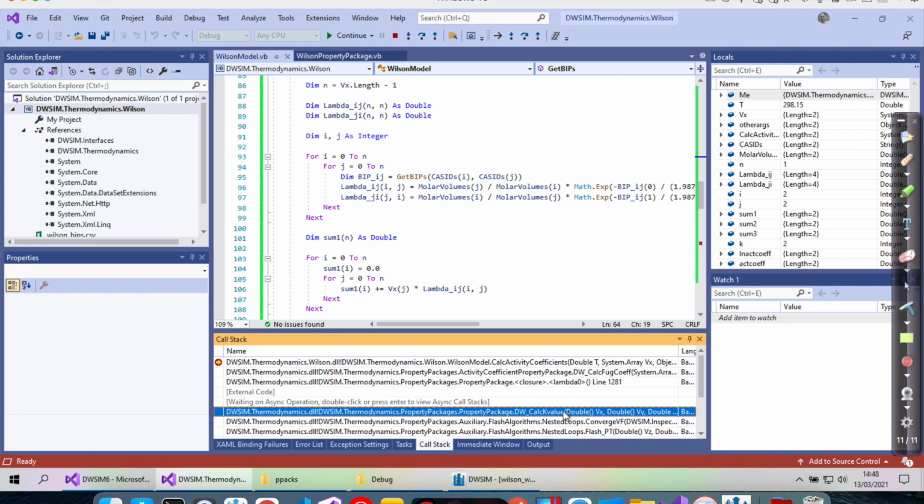I'm not expecting you to do this for every block. Yeah, just for the separator, for instance, you would need this for specific sensors. So I believe it is possible to do, because it depends on what exactly you need. So if you need everything to be in liquid, we can get the composition of the inlet stream and force it to the liquid phase and not calculate the equilibrium.